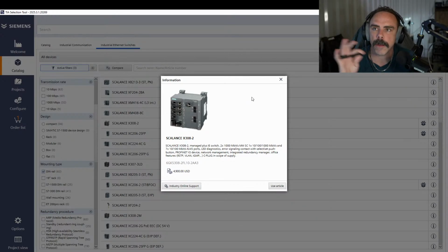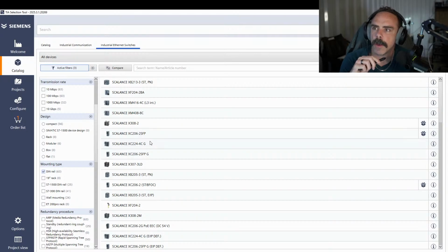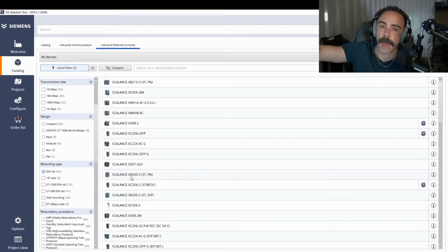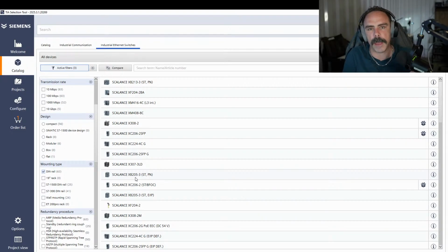With the X series, they are old. You have some XCs and XBs. So we are looking at this XB, and the device in this previous series that I use is an XB208. Well, there is an XC208. Just general nomenclature, the 2 is the series, so kind of the performance level. Then if you have a 208, that's an 8 port. If you have a 216, that's going to be a 16 port. A 204 is going to be a 2 series, 4 port. And then you have your extra stuff, like on this XB205. That's a 5 port with ST, and it's a Profinet version.